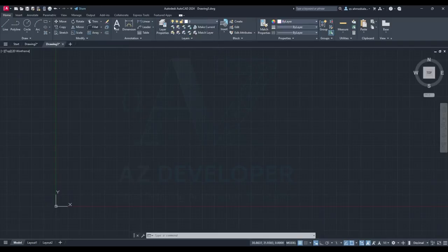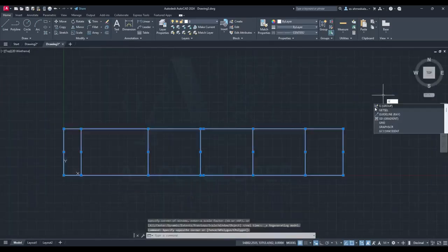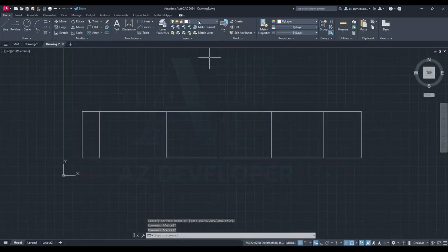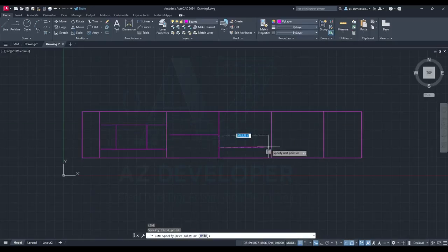Now let's make two example plans. One without profiles, and one with profiles. This grid I'm using is just a guide. It's not required. You can work freely. Just remember these rules. A line in the CAD file will create a straight horizontal beam in Tekla. A polyline will create a polybeam. An arc will create a curved beam. And for profile text, it must exactly match the profile name in Tekla and be placed as close as possible to the center of the line it belongs to.